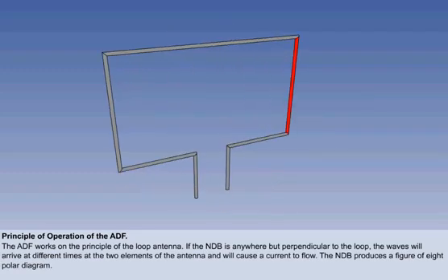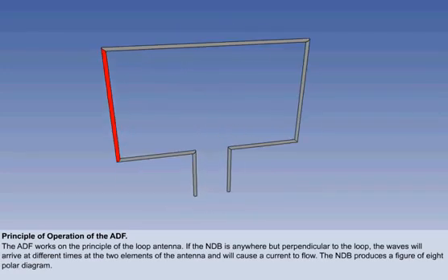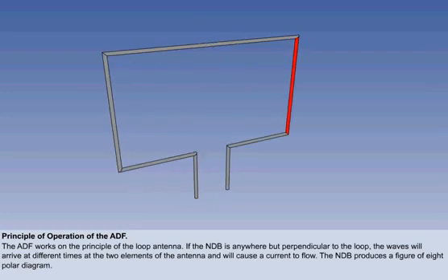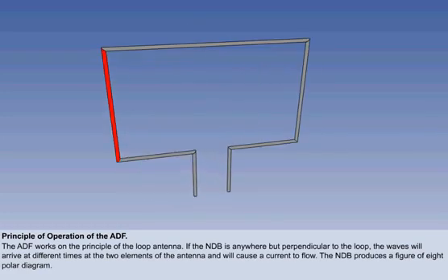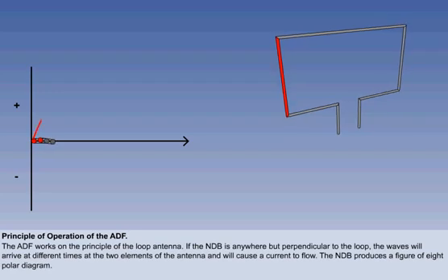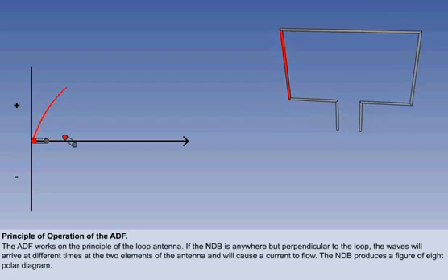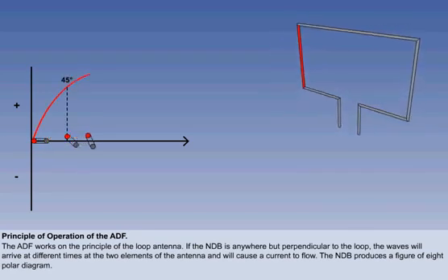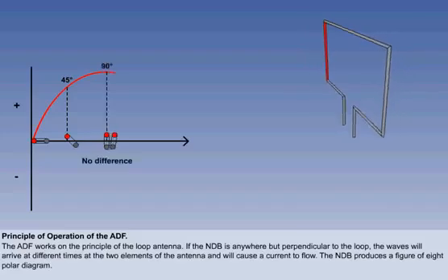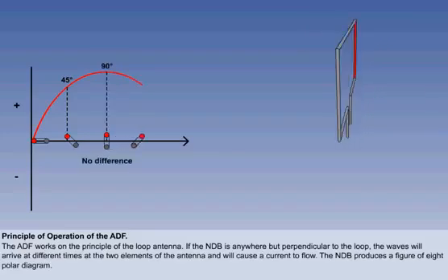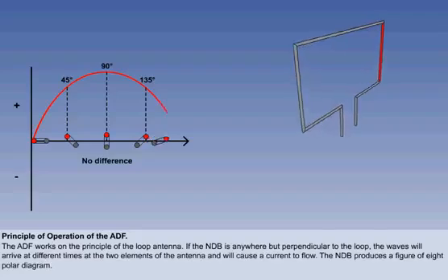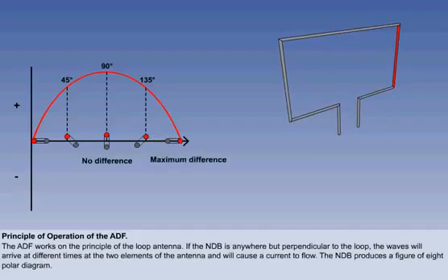In one complete revolution of the loop antenna, each vertical element will turn through 360 degrees. If we follow the red-coloured side of the loop antenna and plot it against the sinusoidal shape of a radio wave, we see that the antenna turns through the positive side of the sine wave from 0 to 180 degrees.